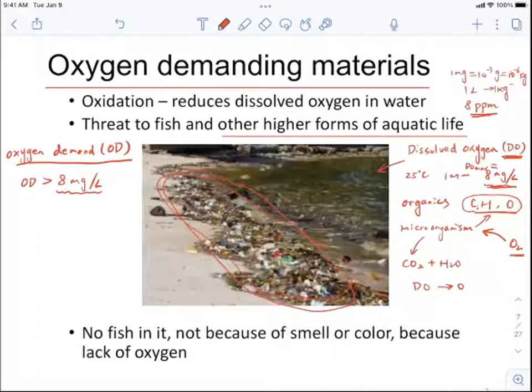What it means is that no matter what happens, the DO, dissolved oxygen, is going to drop down to 0, and it's going to wipe out all the living species in the water, right? It turns out that for industrial wastewater or residential wastewater, there can be a very high concentration of organics. The oxygen demand is typically, let's say, in the hundreds.